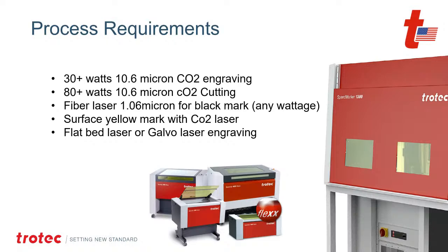Fiber laser for black marking will work. With any wattage of fiber laser, we get a pure black mark onto it, which is an outstanding effect that we do not get on the CO2. And I will explain both types, CO2 and fiber laser, during this section. You get a surface yellow mark with a CO2, and then you get the black mark with the fiber laser. And so again, I will explain each of those. And then a flatbed laser or Galvo laser engraving will work for both styles, so both types of laser systems will work with this material.